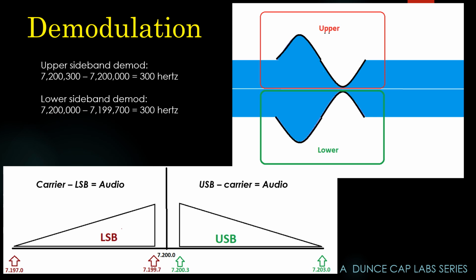Now, those of you that are really familiar with the receiver design, particularly the older designs, know this isn't exactly what the radio receiver is doing. It's looking at the carrier, and the engineer designs the receiver to either decode the upper sideband or the lower sideband. One of the two. Because they're both the same, we don't care which one. The receiver passes the signal through a filter where, on the one hand, it filters the RF energy out, leaving only audio. But it does this through a tricky combination of comparing the contents of one sideband with the carrier.